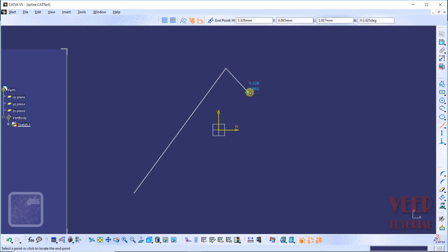So this is the first point, and now I want to draw the second point with respect to the horizontal of this existing line. For this we need to take the references. To take the references, take the mouse onto this line and then drag it. And now we can see the blue dotted line. It means we are taking the references. So I click here. In this way we can take the references.